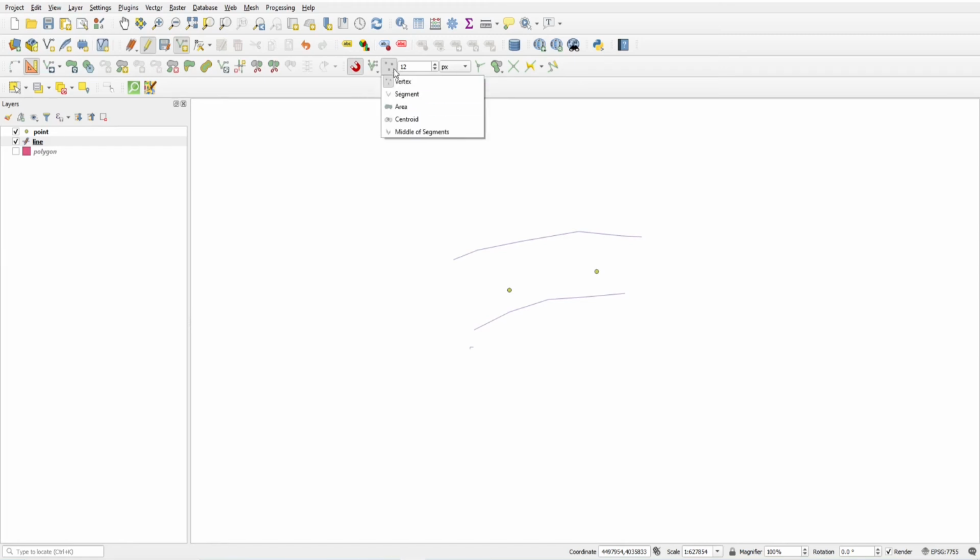This is the type of snapping, and these are the snapping layers. Here you can define the tolerance. This is enable topological editing. This is snapping allow overlap, avoid overlap on active layer, follow advanced configuration, snapping on intersection, enable tracing, and if self-enable is enabled, snapping will also take the current state of the digitizing feature into consideration. So let's start with this.